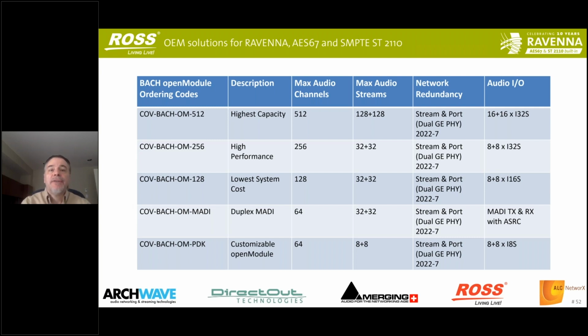We can also handle 500 milliseconds of delay from the physical network for long distances caused just by physics of the transport medium, e.g. fiber cable. This unique innovation is to address long cross-continental networks and is demanded by some end customers of our OEMs and is being used by broadcasters today for long distance networks. One thing I'd like to point out, this technology can be used with the standard minimum output buffers as defined by AES67. So it's very efficiently implemented.